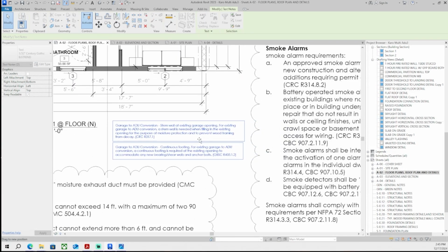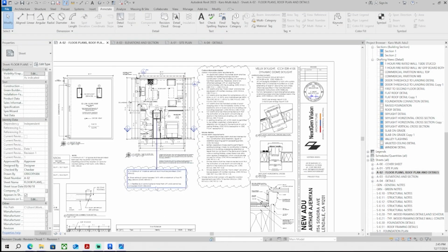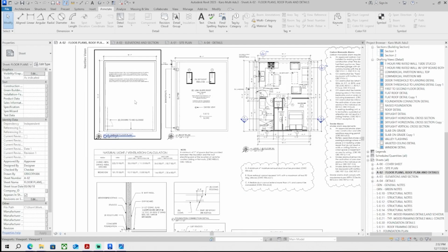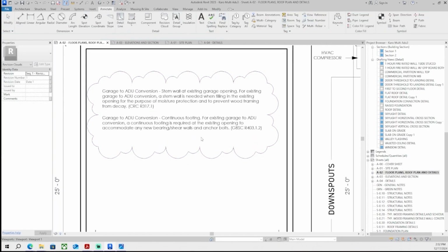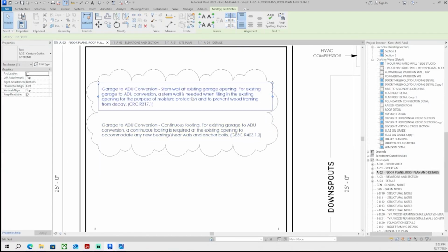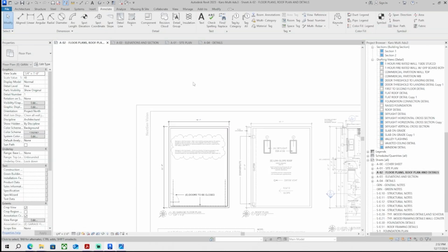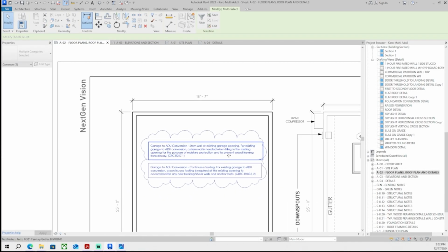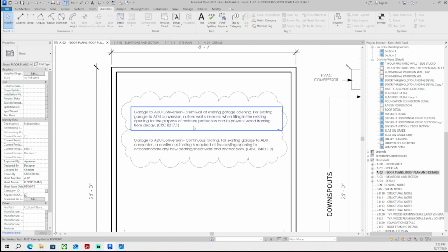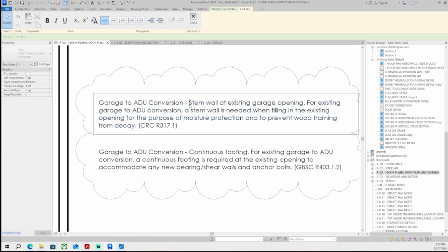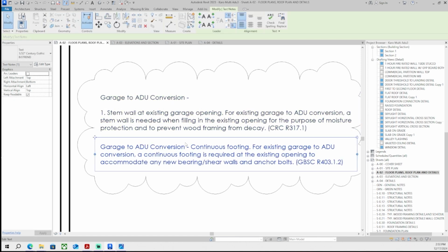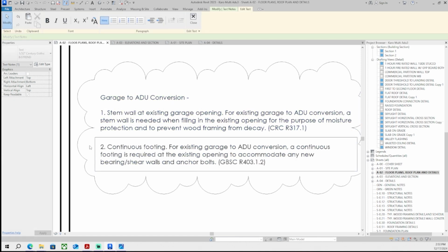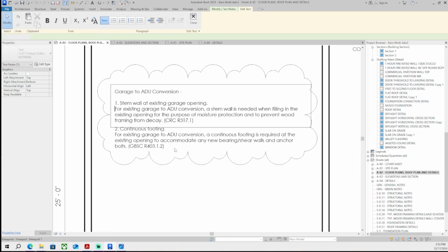Oh, there you see the line of ventilation calculation. And the notes, you know, do them off the sheet, bring them onto the sheet. A lot of the part of the job is arranging your sheets so they're legible. You'll see I'll put revision cloud so the plan checker can see what has been updated as a result. And it's not just the revision cloud, it's the notes on the sheets telling them where they can find it, and the revision cloud, making it as straightforward as possible to review.